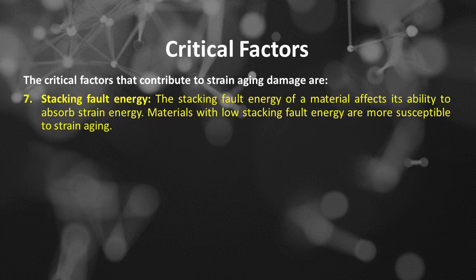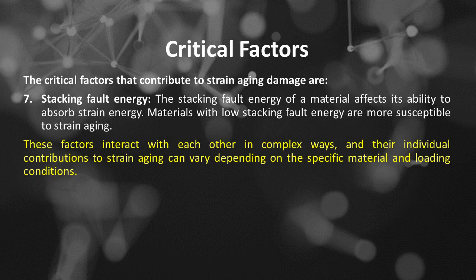Number 7 is stacking fault energy. The stacking fault energy of a material affects its ability to absorb strain energy. Materials with low stacking fault energy are more susceptible to strain aging. These factors interact with each other in complex ways, and their individual contributions to strain aging can vary depending on the specific material and loading conditions.